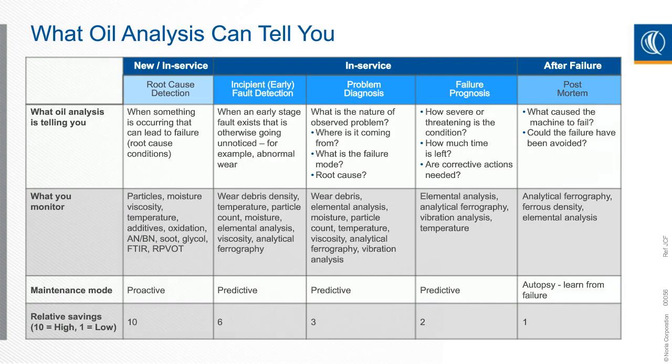So in order to help you figure out what questions you want answered, you need to know what oil analysis could potentially tell you. Now, there are different stages in which you may want to perform oil analysis, and some are going to be more cost-effective, with more potential savings in return, such as testing new oil or testing a machine before it's failing. So when something is occurring that could potentially lead to failure, you're going to be looking for some sort of root cause in oil analysis.